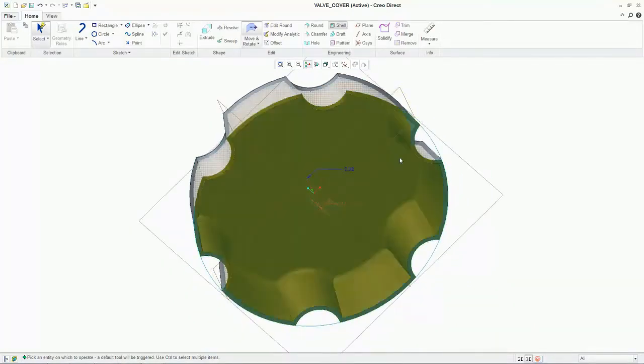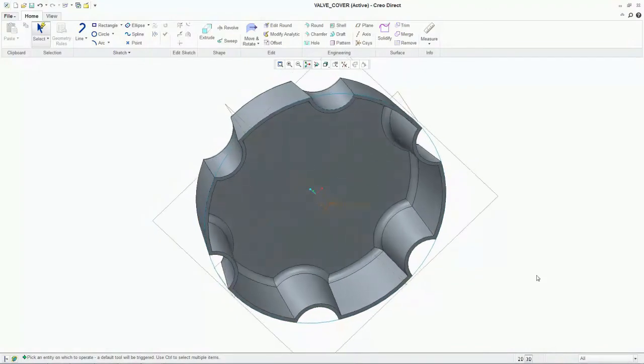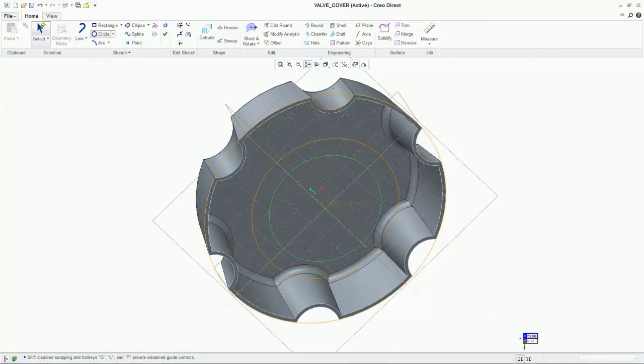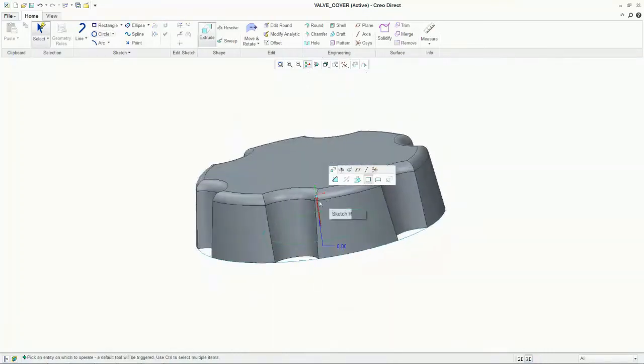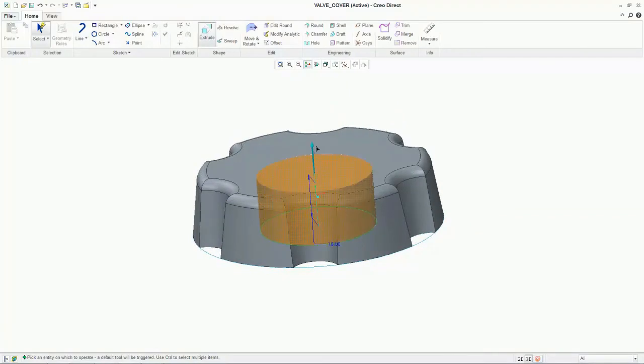By selecting a sketching operation, such as circle, then clicking on the surface plane you wish to sketch, we are automatically brought into the 2D sketching view. We'll quickly draw two concentric circles that will become the outer and inner radii of the downstem, respectively. Switching back to 3D, we will now extrude these smaller circles slightly through the top of the cap.